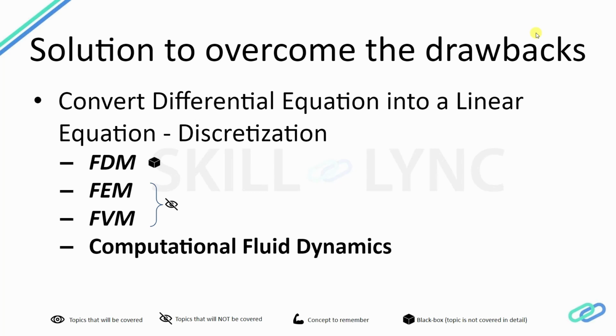A process called numerical discretization is employed to convert the differential equations into linear equations. There are several methods to do it: finite difference method, finite element method, and finite volume method. In fact, the point-based derivation that we had shown earlier is essentially what the finite difference method is all about. Though we did not get into it in a detailed way, looking at the derivatives at a point level and then deriving an equation based on that is the fundamental concept behind the finite difference method.